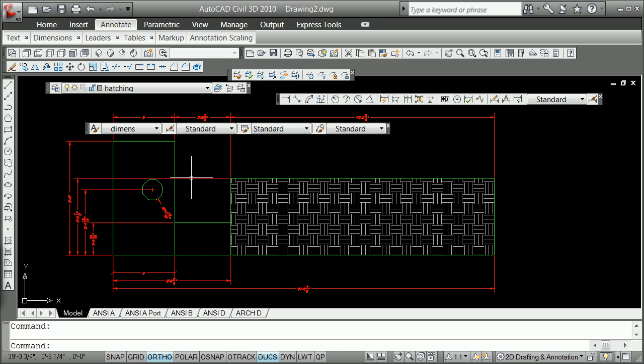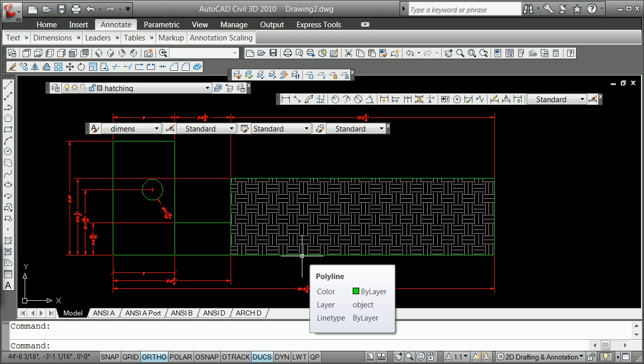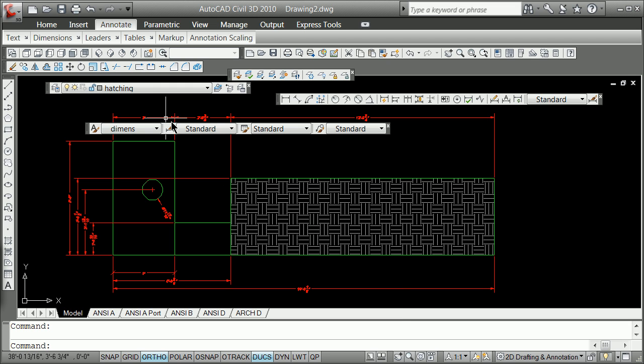I'll do a couple more hatches here. I'm going to take the same hatch here, but go ahead and do it at a different angle. Hatches are great if you're doing black and white stuff, because you can't differentiate with color. So anything that's really being laid out well to differentiate will have one hatch particularly, and if you're using color, you'll have different hatches for different materials. It's used a lot, as Lindsay Lohan would say in that great movie, a lot in architectural work for your typical sections, cross sections. So we're still in hatching.